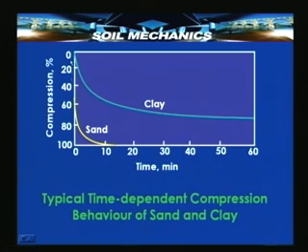Here the compression is expressed in terms of percentage of the total compression that takes place for any given load increment, and you find that even after 60 minutes this clay layer is showing considerable rate of compression. In fact, in practice it is not in 60 minutes, this graph shows only the compression in percentage over 60 minutes, but this is a phenomenon which goes on taking place over several hours, even up to 48 hours.